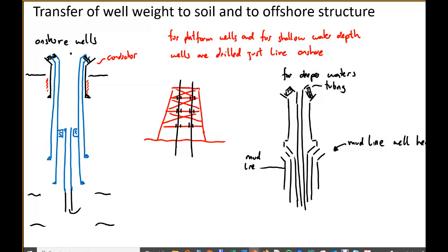They're much thinner than the inner pipe, and they're also much bigger, so you would need a very big thickness to make them tolerate that pressure rating. So these seals are there to protect against that pressure. This pipe won't be exposed to that pressure, because if that happens, it will burst. Okay, so you have the hanging part, but you also have the seals, which are supposed to protect the outer layers from the pressure on the inner layers.